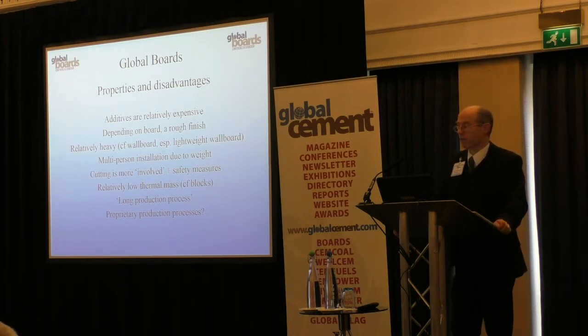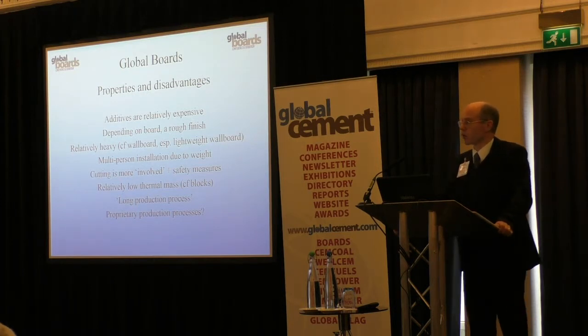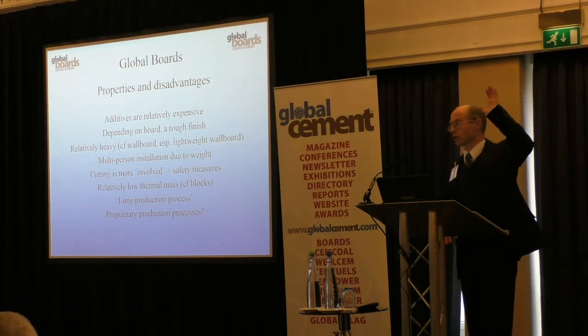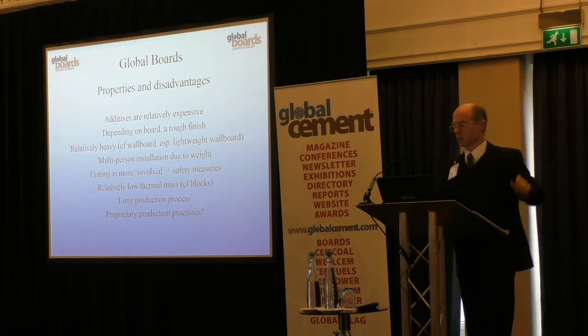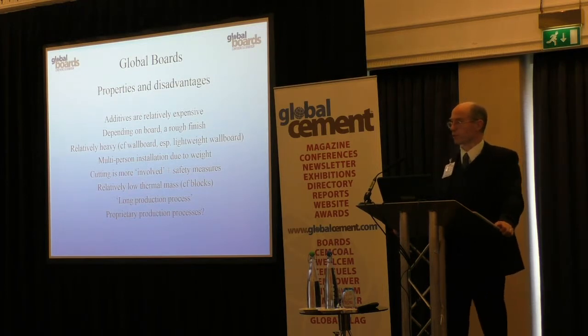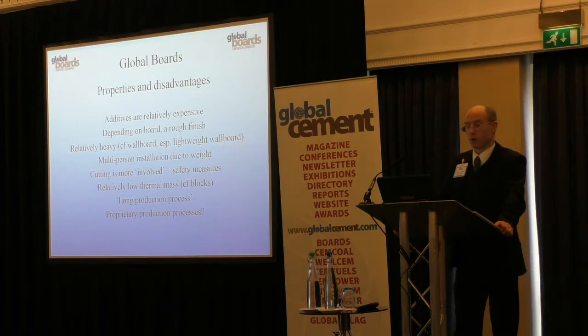They can be relatively heavy, particularly compared to the lightweight wallboards, which I don't know if you know, but there's been a very strong trend in the United States and progressively around the world, starting from the States, towards decreasing board weights, towards what many call one-man boards, or one-person board, I should say, where one person can pick them up, move them around, and put them in, compared to two that would be required for a heavier board. So typically with a cement board, you would be looking at a heavier board and two people or more sometimes to install them due to their weight.